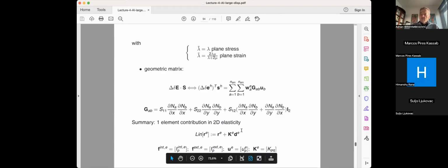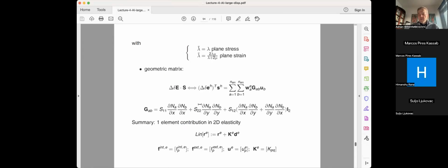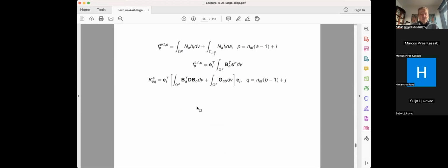And so when all said and done, you have your internal force vector and you have a tangent stiffness matrix with both material and geometric terms. So this will be a typical element, and you can see nonlinearity arising because of the nonlinear dependence on the second Piola-Kirchhoff stress and the nodal displacement. In particular, this is a cubic function. And then linearizing, you have these 2 parts of your tangent stiffness. There's one part which is material, and the other part is geometric. So this geometric part, you can see, depends on the stress. Hence, you can introduce pre-stressing to give stiffness to your structure, even if it's very slender. By pre-stressing, this is the typical feature of this large deformation.